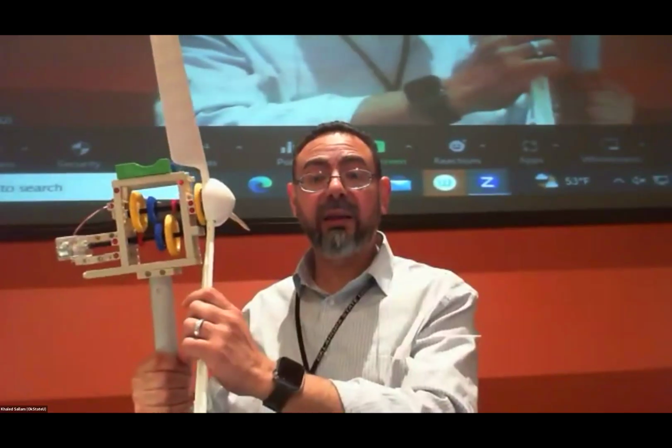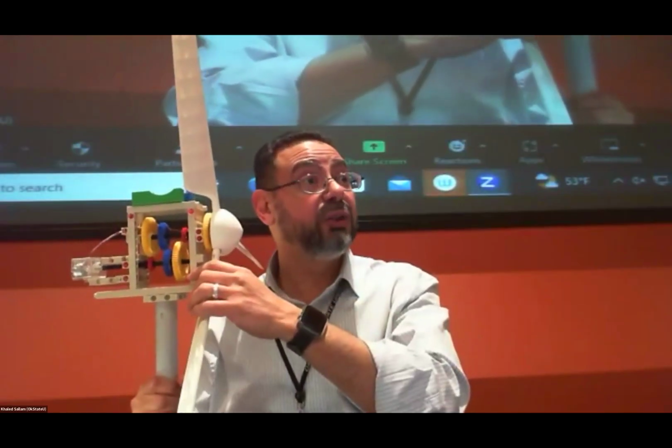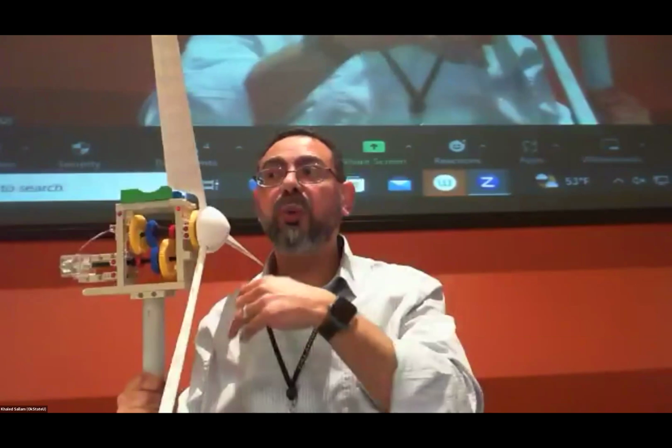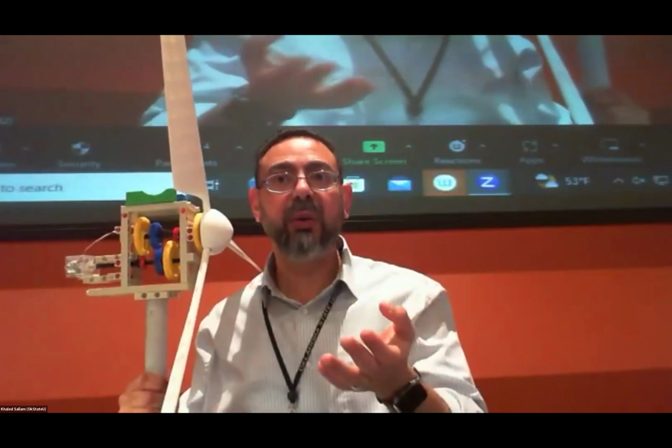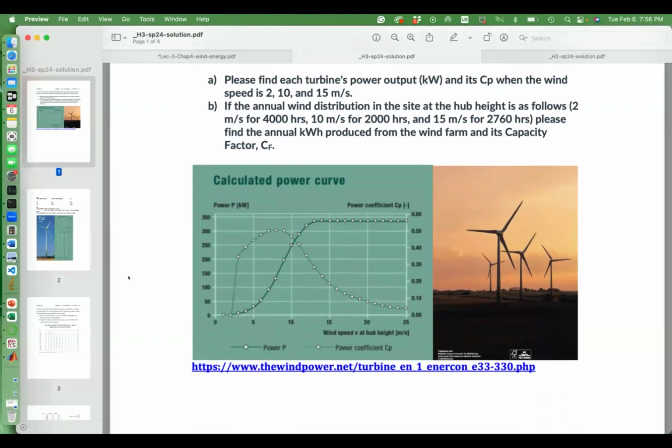And one more thing before we leave. So now we said that for optimum performance, that plate needs to be at exactly the right direction for the wind. But if they want to spoil the performance, if they don't want all the wind to be harvested optimally, they don't want all that power, they play with that angle. That pitch angle is controlled from inside here, so that they meet the wind at the wrong angle. And therefore, that's crazy, right? But that's what they want to do in order to cap what? To cap the output power, right?